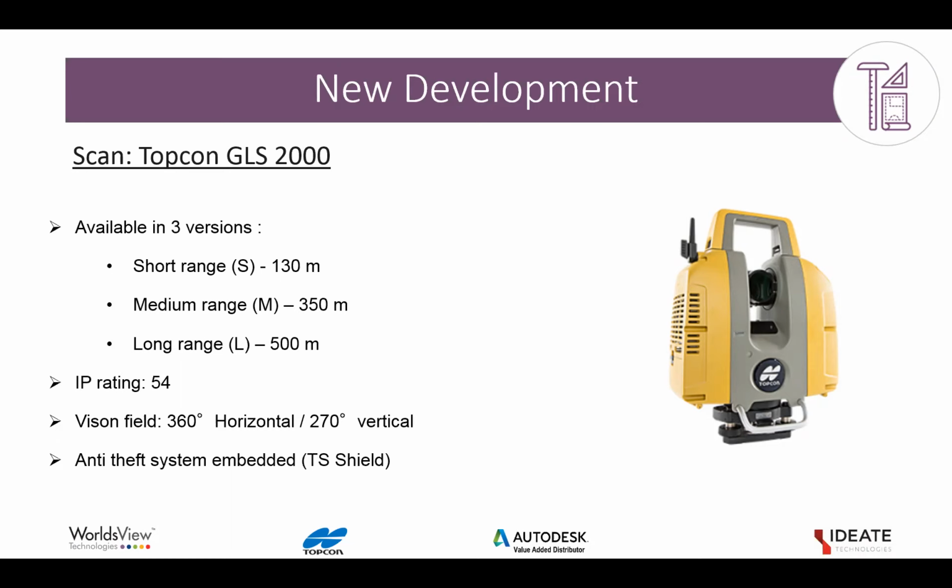Let's imagine you want to scan a building that is behind trees, and the leaves are hiding some parts of the building. You can set the GLS 2000's laser to higher pulses so that it can penetrate the leaves and target the building behind them.